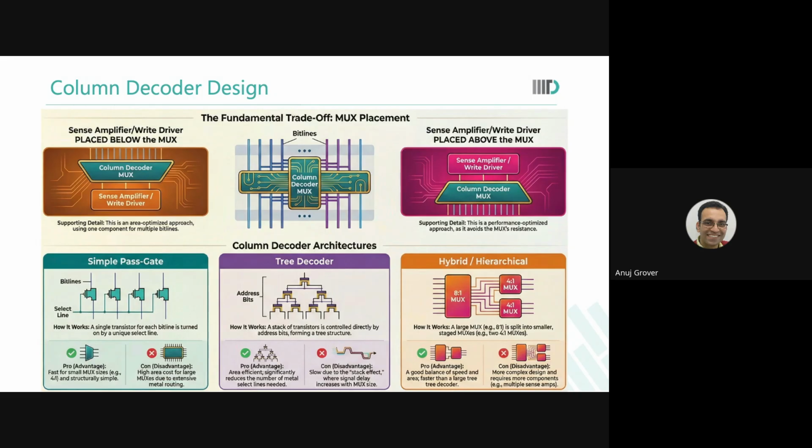It impacts delays a little, which is acceptable. But it saves power. Because if I keep it pre-charged, the bit line will continue to leak throughout the time when this ROM is not even being used. And ROMs are used sparingly. So it makes all the more sense to do it like that for ROMs.